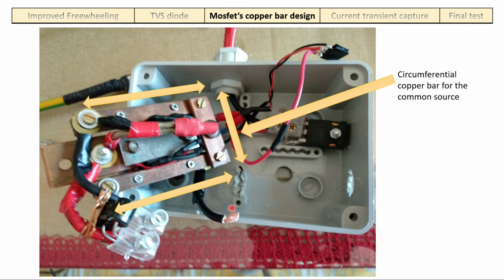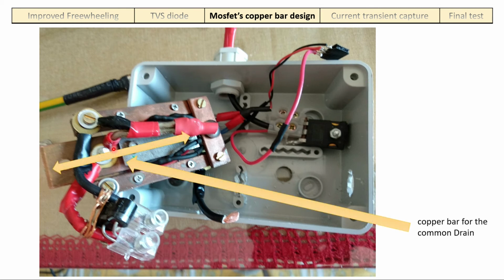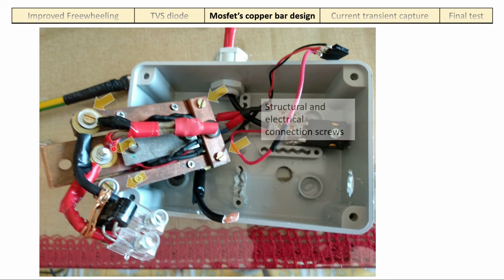I prefer to put 3 of them, even if just one is enough. So as I told you, the external part of the copper bar is the connection of the source of the MOSFET, while the drain is the inner part. The screws utilized here are electrical conductors. At the same time, they have a structural action over the bar.